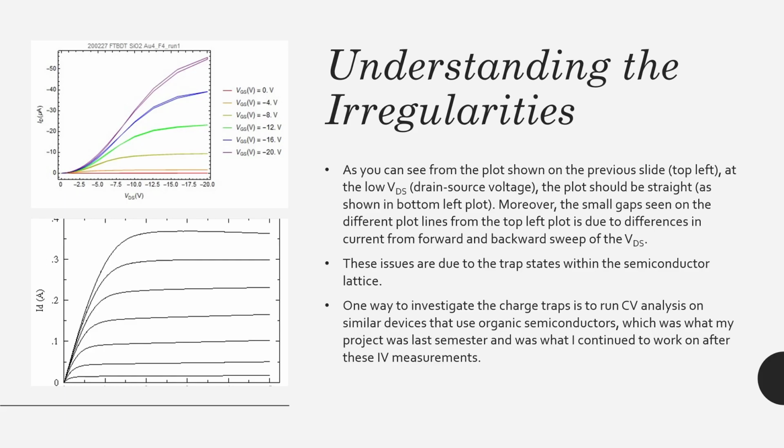Both these issues, the low drain voltage, drain source voltage curvature, and the gaps between the forward and backward sweeps, are issues due to the trap states within the semiconductor lattice. A way to investigate the charge traps is to run CV analysis on similar devices that use organic semiconductors, which was what my project was last semester, and what I continue to work on after these IV measurements.